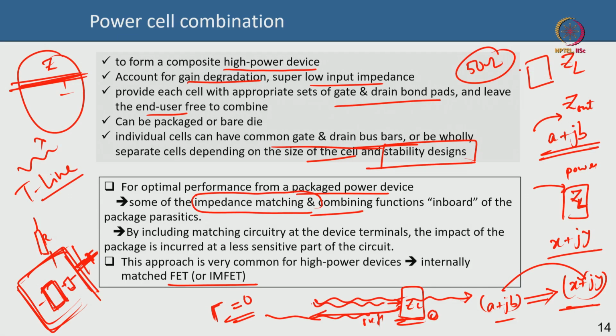So, the impedance circuit has to be designed for a 50 ohm terminated impedance. What I mean is that, suppose your output impedance is 20 minus 30j ohm, you need to add a resistor capacitor network that will give you 30 plus 30j. If you add them together, 30 plus 30j and 20 minus 30j, the imaginary parts will cancel out, and you will get 50 ohm. So, you have to implement 30 plus 30j in an impedance matching network inside the package, that is all it means.